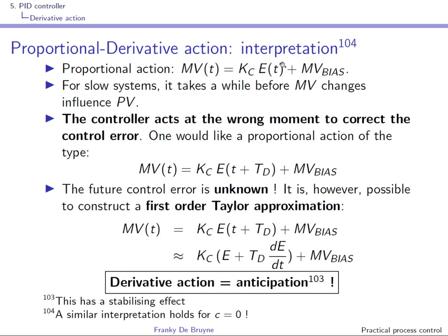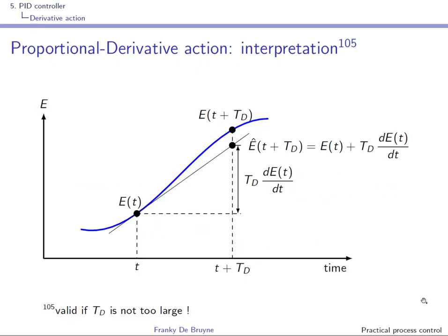What we have done here is an interpretation where C is equal to 1. You can see it over here, because we have the standard control error, and we have started from an interpretation where the proportional error was with B equal to 1. But you can do similar things when C is equal to 0, but then you have to work on PV instead. So here you have this graphical representation.